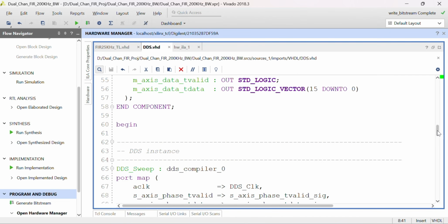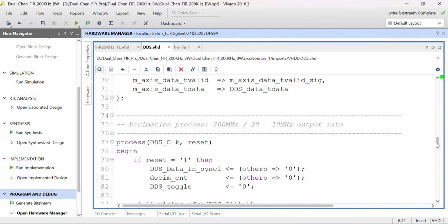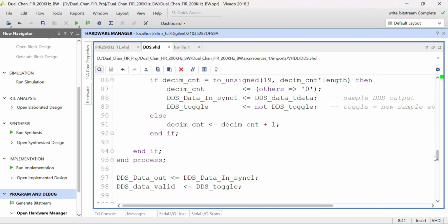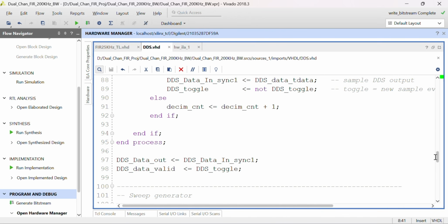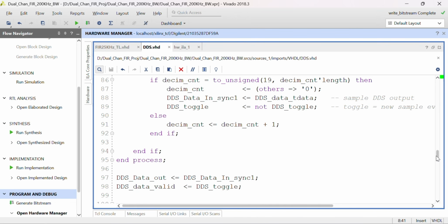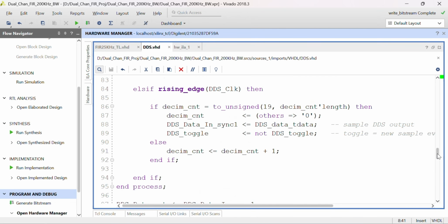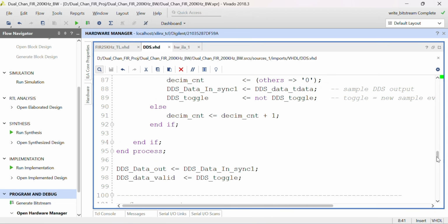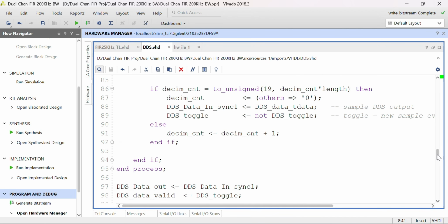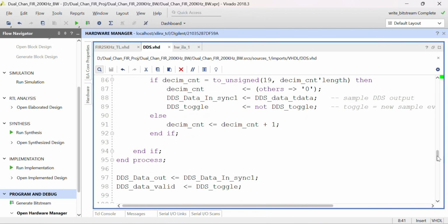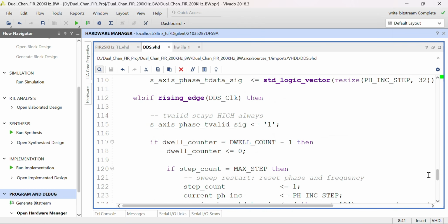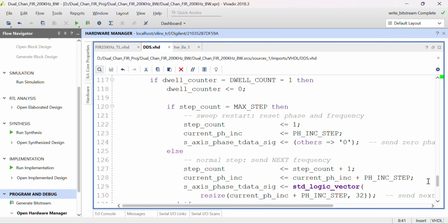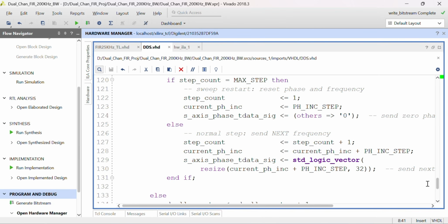Then we are doing our sweep based on, as I mentioned before, the start and the end of our sweep. We start from 100 Hertz all the way to 500 kilohertz, and then the persistence, for how long we want each frequency to persist. That's pretty much it. I went through this code last time in my previous video, so please go back and take a look if you have more questions.